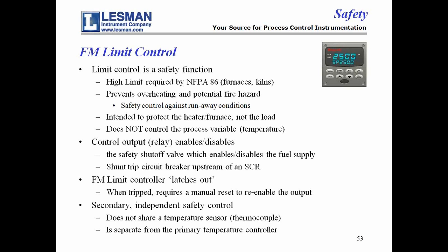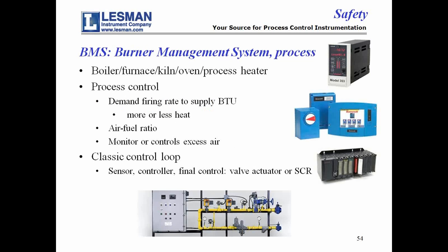It's its own safety controller. We got burner management systems out there, and burner management systems have two aspects. This slide shows you the process aspect, where it actually does the process control, which is regulating the demand firing rate that supplies the BTU, gives you more or less heat. It can do air-fuel ratioing, monitor or control excess air. It's a classic control loop. Okay, this is the process side of BMS.